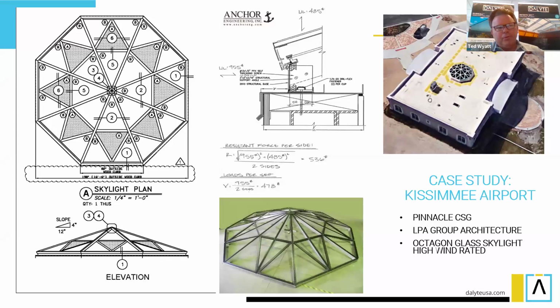But through structural calcs and stamped calcs, we can show that our units can withstand the wind loads. So this one was unique at 165 miles per hour. The unit actually had almost a 500-pound uplift from those forces.